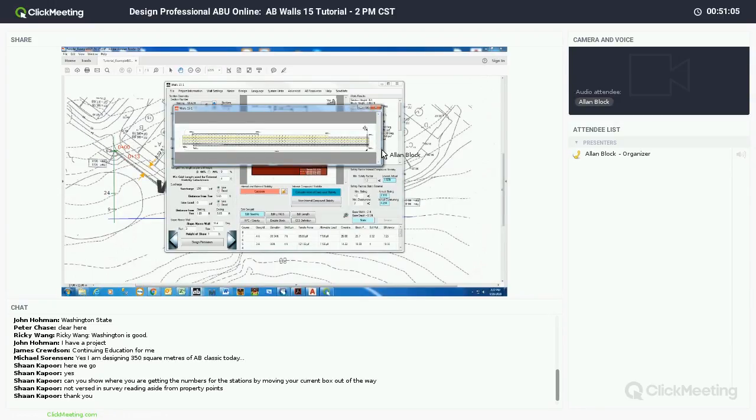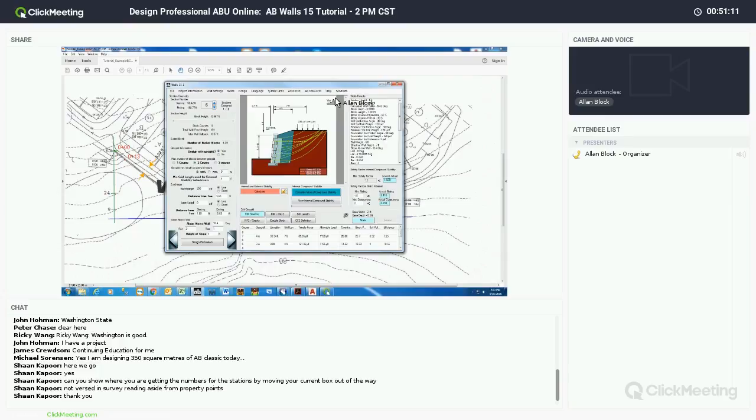It's a good thing to look at to see what wall you're doing if you have to make any changes. I'm not going to view it, so I'm going to close them out. And if I don't want them to pop up again, I'm going to just turn off this yes construction elevation button, and I'm going to just turn it to no, so I don't have to see that again.